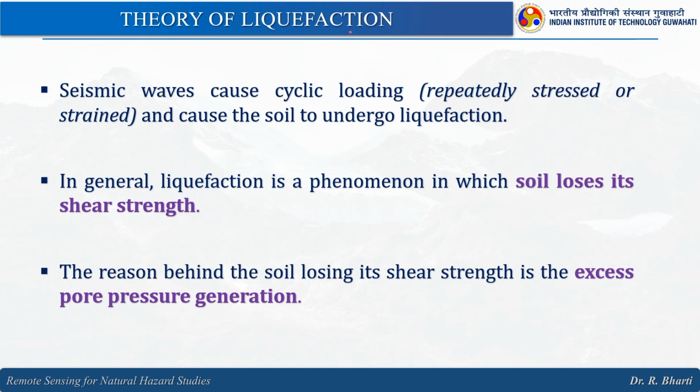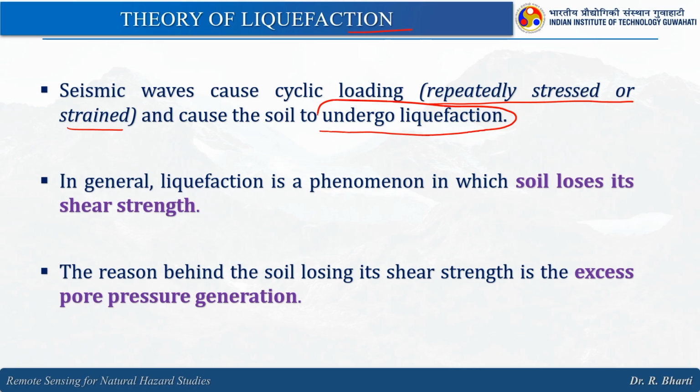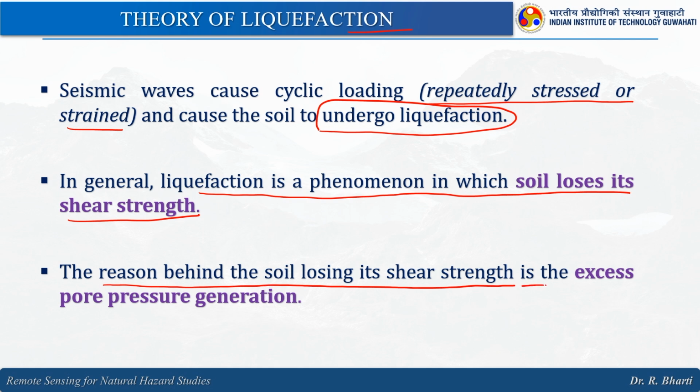So, the theory of liquefaction says seismic waves cause cyclic loading, which is basically repeated stressing or straining, and cause the soil to undergo liquefaction. So, we will try to understand what we mean by liquefaction. In general, liquefaction is a phenomenon in which soil loses its shear strength, and the reason behind the soil losing its shear strength is excess pore pressure generation.